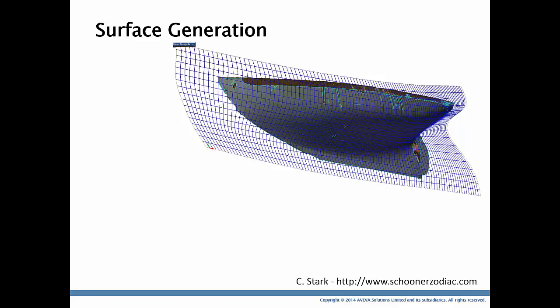For example, as a living surface, it's not really got the ability to be modified. It's just got too many data points. There are also features on the hull form that we're not really picking out, for example the rabbet line and the stem aren't really being captured in this surface definition. Which is a shame because it's probably going to be a fairly good quick approximation.